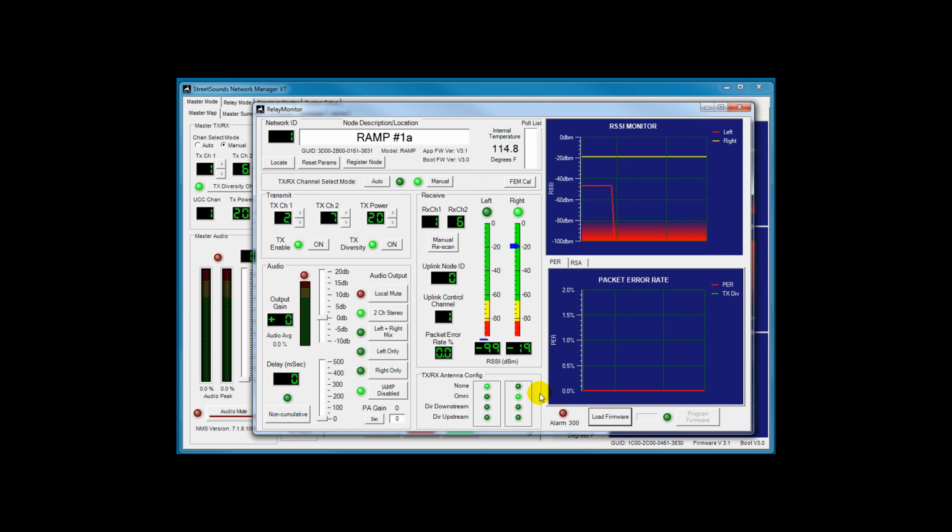That's a little advanced, but we do have both frequency diversity, spatial diversity with antennas, and time diversity. So there's triple diversity in the transmission, which makes the link much more secure and stable. If you do happen to drop one of the 2 packets, you'll see a green blip, a green spike. And that's fine. It didn't get the first one, but it did get the second one.